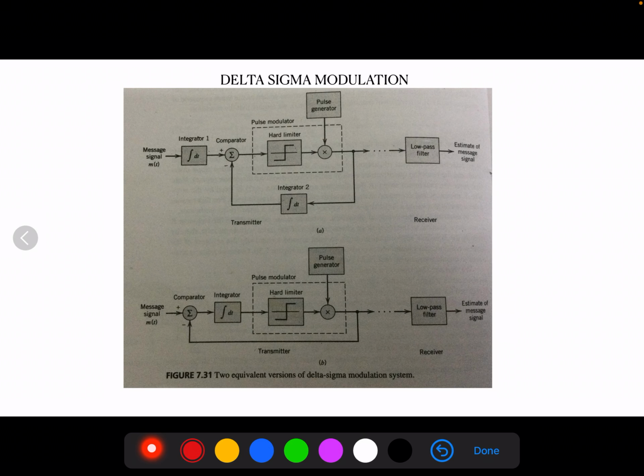As we have previously mentioned, the quantizer input in the conventional form of delta modulation may be viewed as an approximation to the derivative of the incoming message signal. This behavior leads to the drawback of delta modulation in that transmission disturbance such as noise results in an accumulative error in the demodulated signal. This drawback can be overcome by integrating the message signal prior to the delta modulation. So, the use of integration is the manner which will be described now